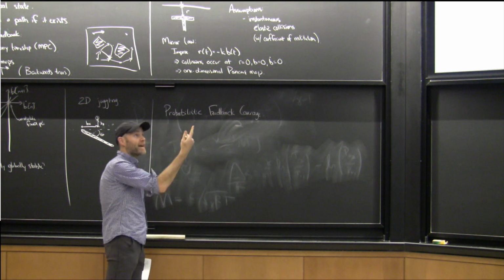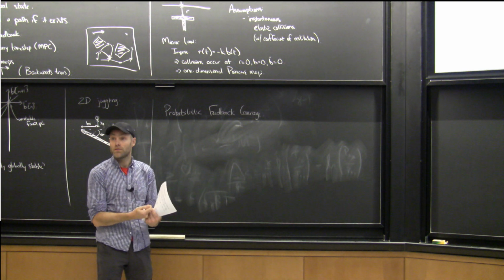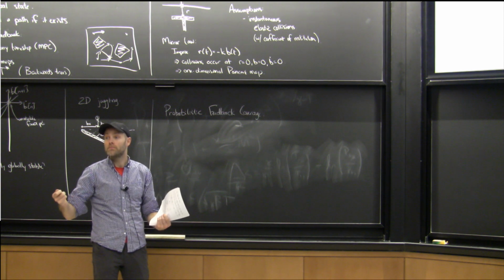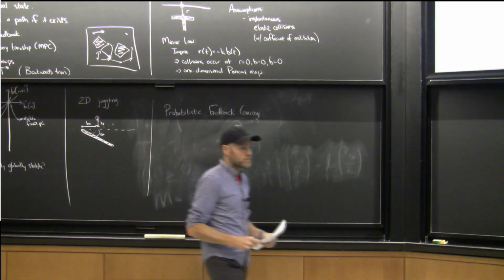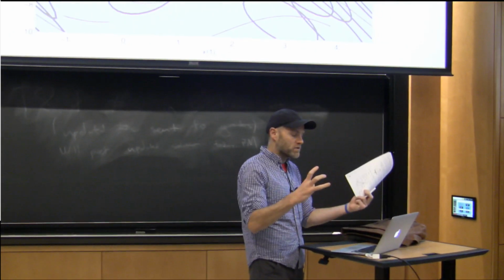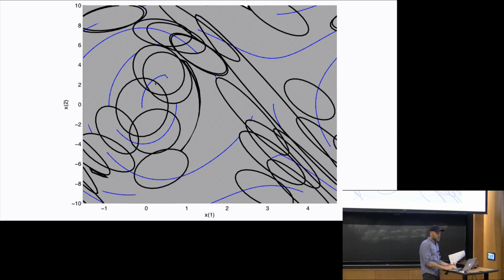Which says for any x that is inside, for which a path exists to get me from that x to the goal, it will eventually be inside the region of attraction of my controller. And the way to think about this, we're approximating the reachable region, the initial conditions that can possibly eventually get to the goal, with ellipses, which may or may not be a very efficient representation for the true reachable set. But we can always eventually make enough ellipses. They might have to be arbitrarily small to get the last little nooks and crannies out, but we can always eventually fill the space.